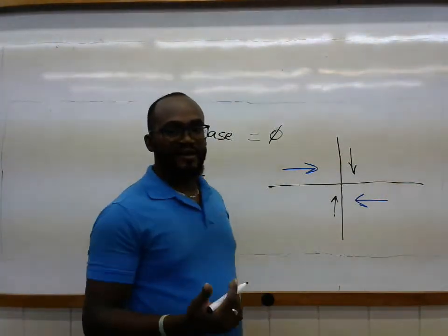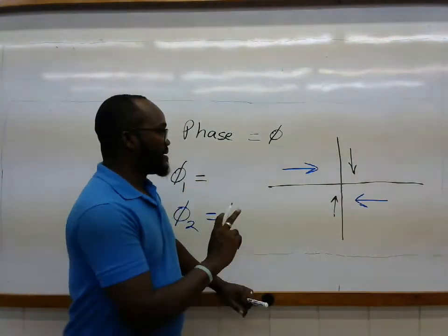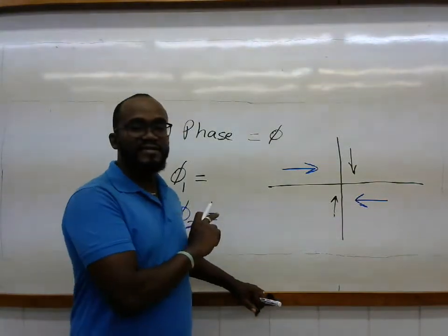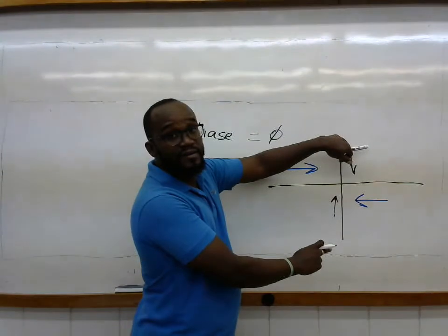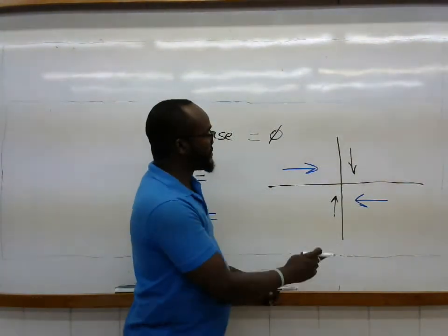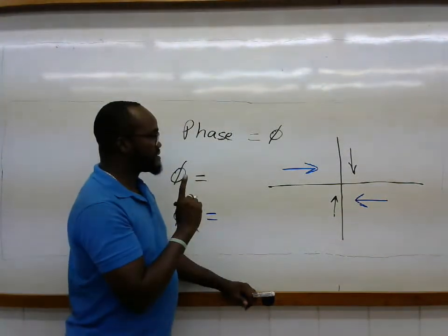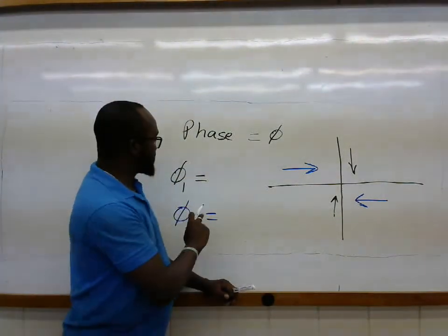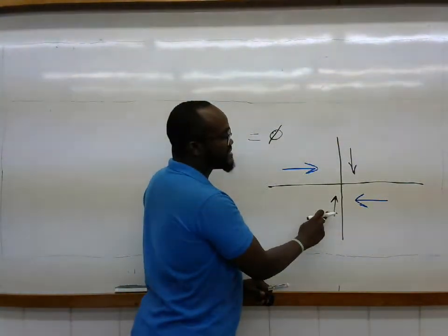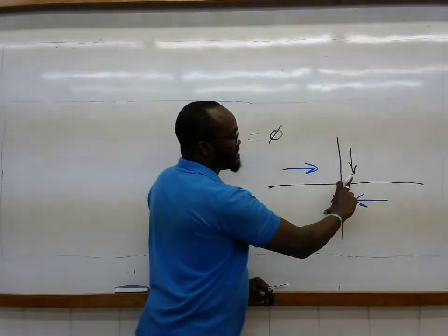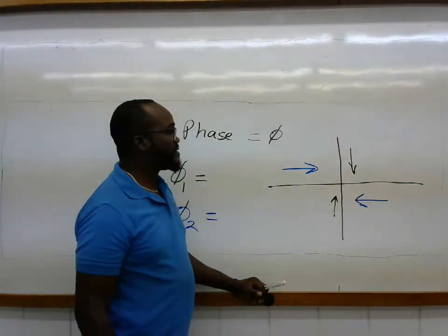And just like the cycle length and intervals, these have times. Now, the phase is not the time strictly for the green. It includes the amber. Okay, so a phase change occurs at the commencement of the amber. So for example, you may have the north-south proceeding. As soon as it turns to amber, then the north-south phase terminates.